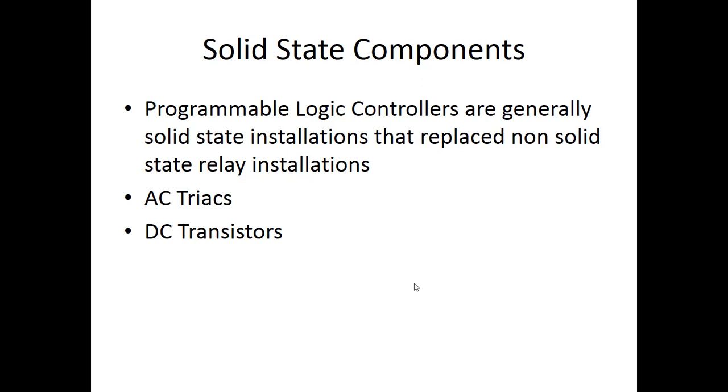We talked about solid state. They're solid state. They don't have any moving parts. Traditionally, the switching mechanism for AC would be triacs, and the switching device for DC would be transistors. And if you run too much ampacity through these, you will blow these up.